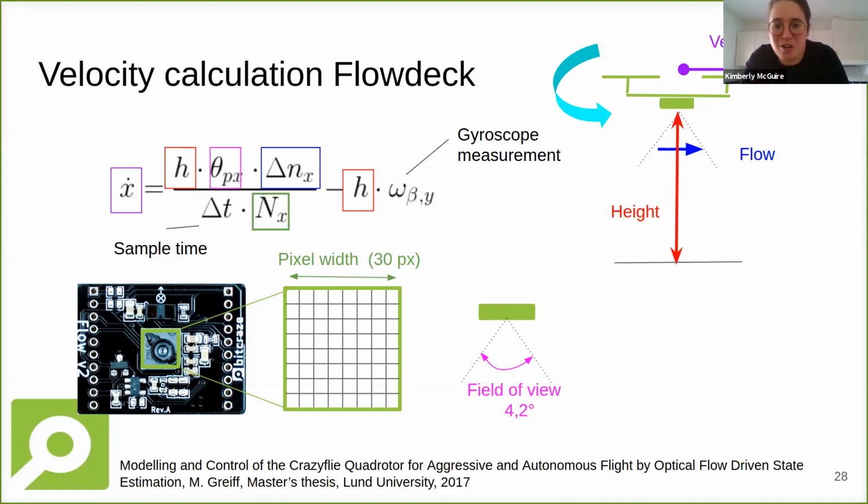All right, so Tafat is asking: while not moving, can we also get information on the rotation from the optical flow? Yes, you can. If you're assuming that you're not moving and you see a rotation, and you know what the height is, then you can also infer the actual rotation. So in that sense, you can also get the attitude.